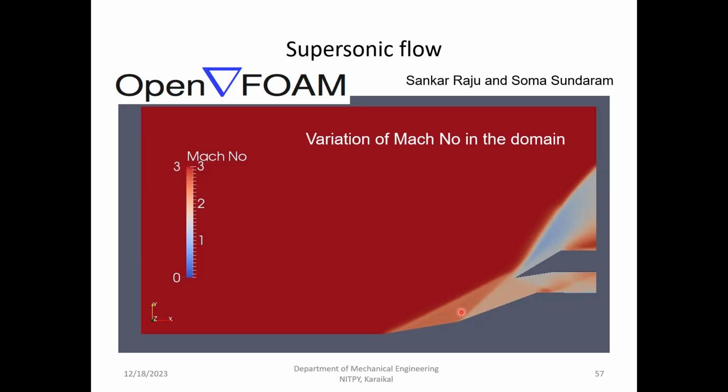But the only thing is, in Fluent, if I want to go from SIMPLE to SIMPLER algorithm, all I have to do is change it in the drop-down box from SIMPLE to SIMPLER. That cannot be done here. SST k-omega to k-epsilon model, a single click will do it in Fluent. Here, you must go and get the k file folder, epsilon file folder, put it in your directory, and then change the values accordingly. So that's the major difficulty of OpenFOAM, but still it's a good tool to work on.